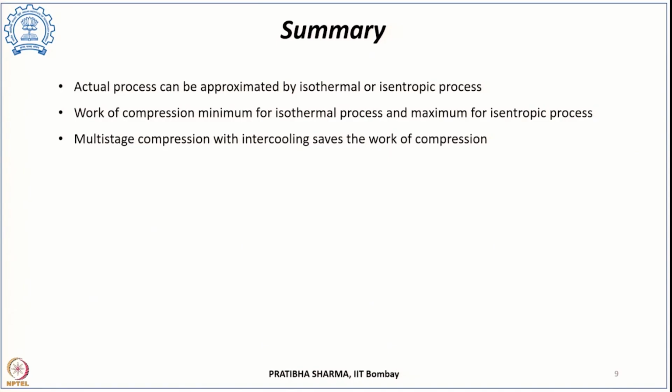In this class we have also seen the work of compression, considering whether the gas is an ideal gas or a real gas, which type of thermodynamic process we have modeled, and the compression work required for multi-stage compression with intercooling. Multi-stage compression with intercooling has the advantage that it can save the work of compression and approximate a nearly isothermal process, such that the temperature of the process is the same after every stage of compression. Thank you.